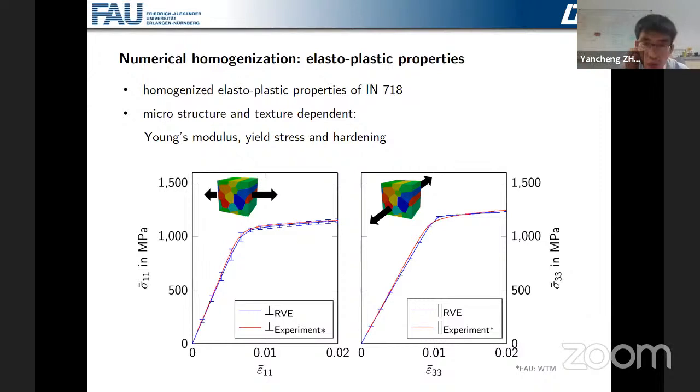Okay. And also continuing about this one: is the temperature for the experiment room temperature or a relatively high temperature? Because the state is quite different. At room temperature, I think the residual stress will have a great influence on the traction curve. At high temperature, there is less influence. I don't know in your case here.